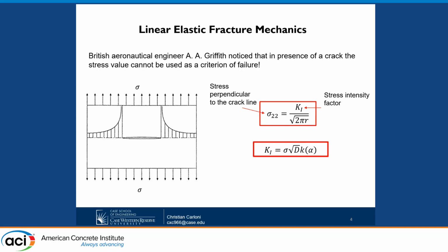So if you were a student, an engineer in aeronautics in the 70s and 80s, there were these gigantic books of fracture mechanics with that K alpha for all the geometries. So when they had the rivets on the wings of the plane, they were looking for the crack near the rivets, what was the K alpha, and they were designing to make sure that that crack did not propagate during the fatigue of the wings, okay?